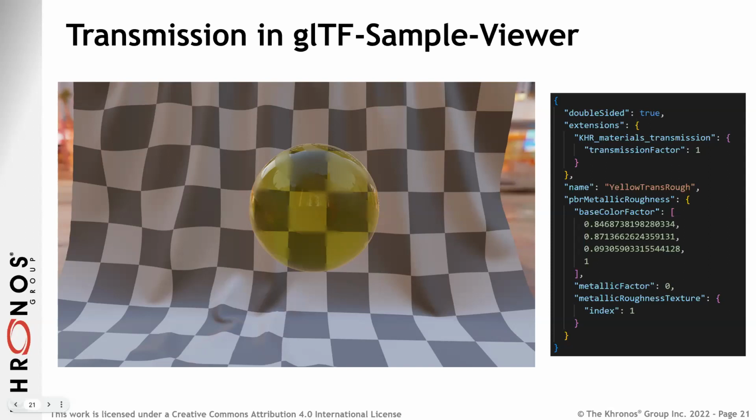And I'll also point out that this being thin-walled, they're typically authored as double-sided being set to true. So in advanced renderers, you'll capture the backside reflections of that transmission sphere as well as the front side. So you have those two transmission surfaces that show up in the render. Okay, so let's see how this fits into the core material model. Let's go on to the next slide.